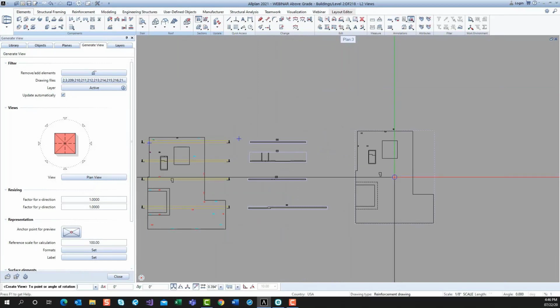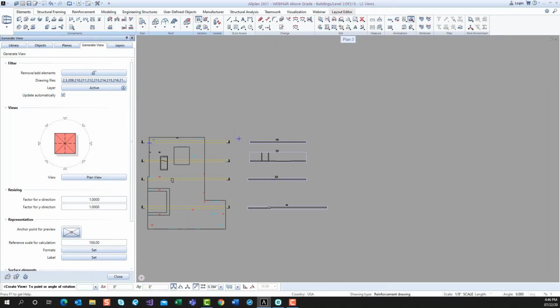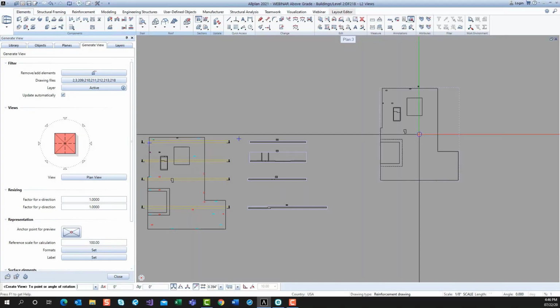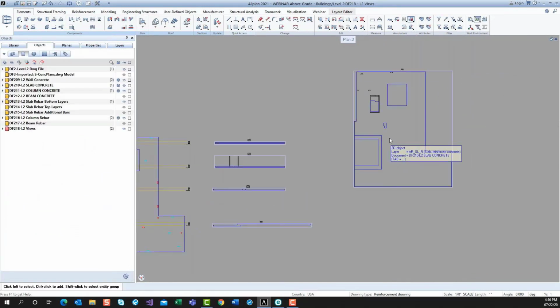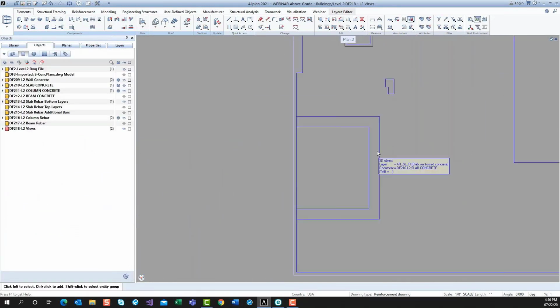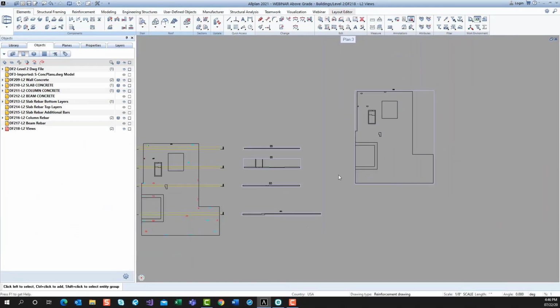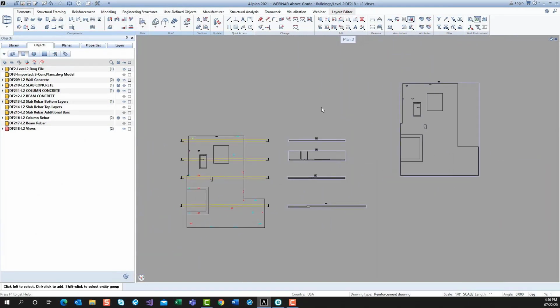Next thing I'm doing here is I'm generating a plan view of that slab. Again, 2D to 3D workflow: when we shape bars and put bars in, we generally have to specify a shape, and we have to specify what we call a range of rebar. In order to do that, we work with a couple of different views. Shape it in one, place it in another. The magic of Allplan puts it into the 3D model exactly where it needs to be, and you're detailing at the same time. All very, very powerful.